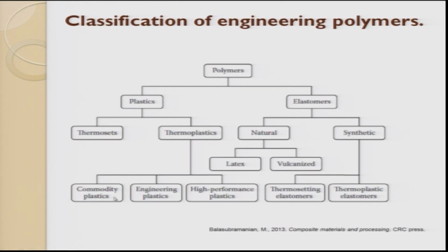Commodity plastics are plastics wherein there is not much load component, and they are predominantly used for household applications or for some entertainment. For example, making a closure for a machine tool is commodity plastic, wherein it does not take any load; it is a secondary structure. The next one is engineering plastics, which have high strength and are also taken to a service condition where temperature is involved. High performance plastics are for endurance cycles, and we can look at these types of plastics for such uses.